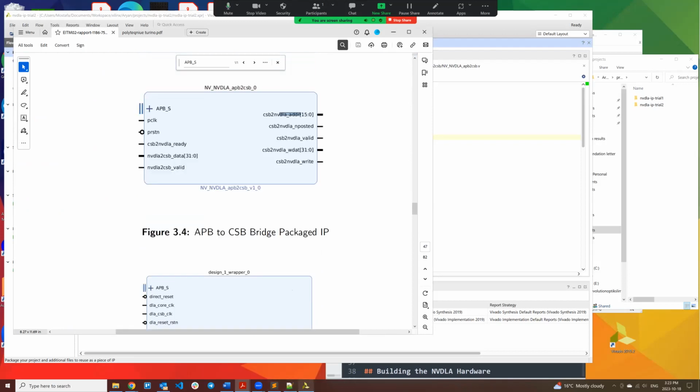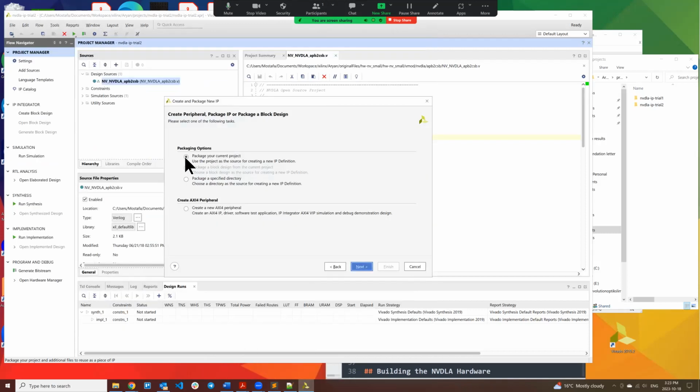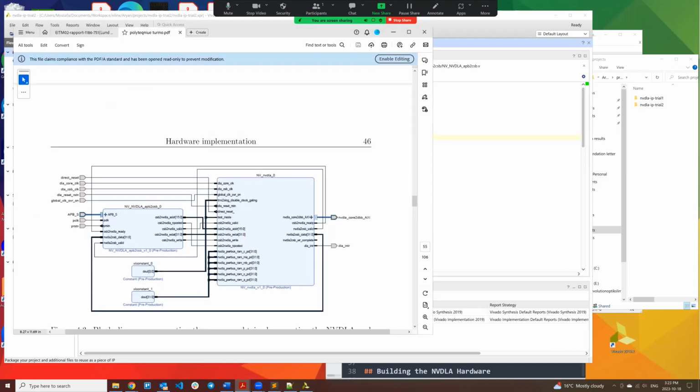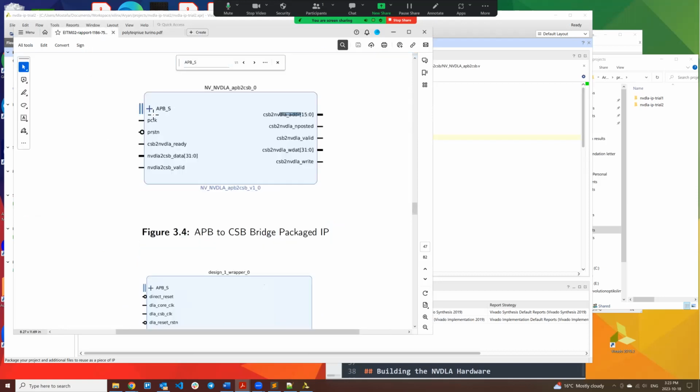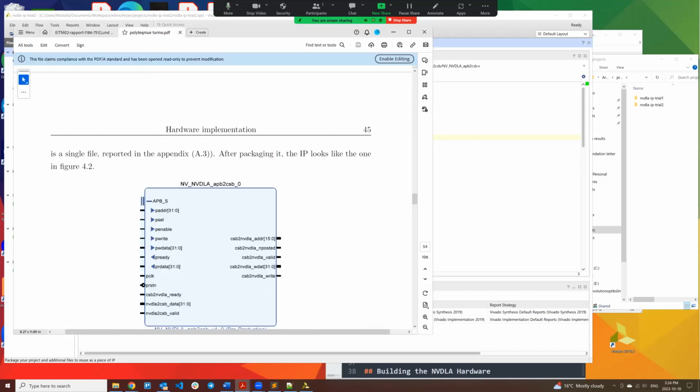So if I go here, if I click this one, there's not gonna be any AXI input. Look, we need this AXI input for this module. If you look at that, it requires an AXI input. This is an AXI input, and this is the wrapped model. Look, this pin is an AXI. This pin is an AXI. What happens if you integrate an IP without an AXI input master or slave? It's not gonna be connectable to any other modules inside your block design.